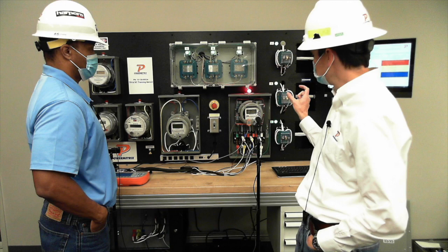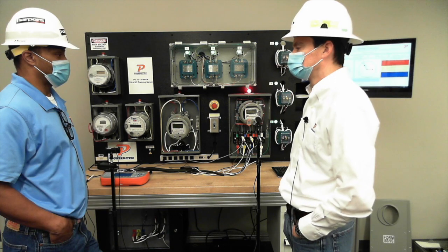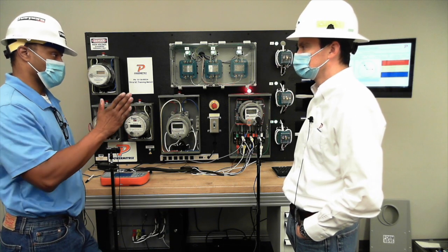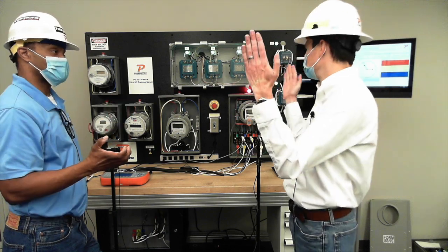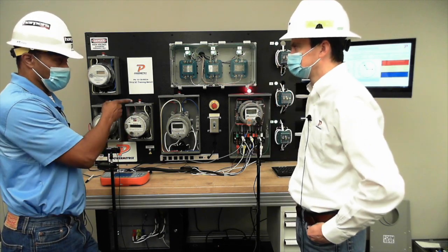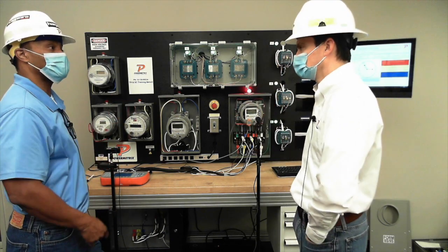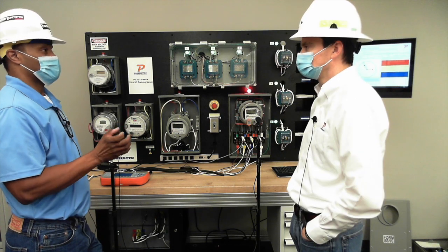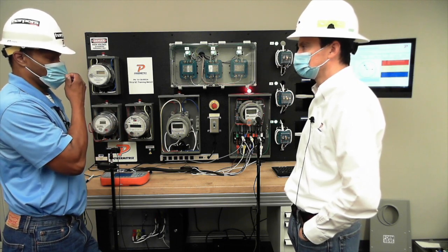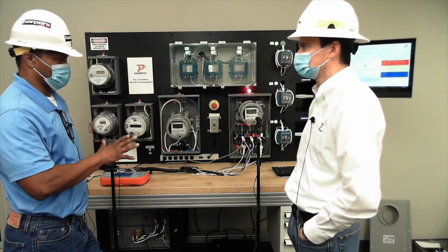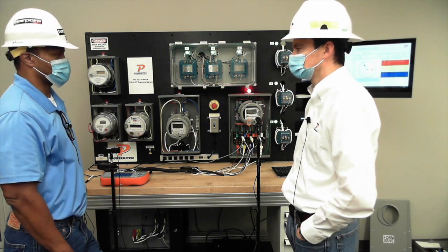Well, you can do that, but you've got to think about it. If it's a large usage of kilowatt hours, then you're shorting yourself. So if it becomes a number that's really, really big, then you want to leave it as is. You're just going to have to sit there and wait. But if it's at a point where they don't consume that much, then you can program the meters like that. But normally, a lot of people just program it to five whole numbers on the kilowatt hours.